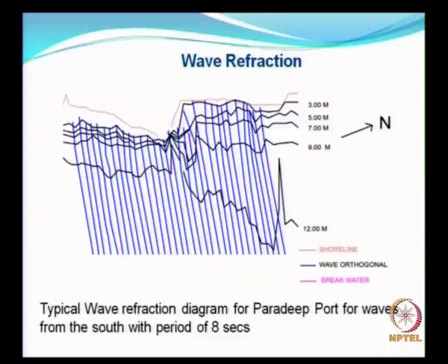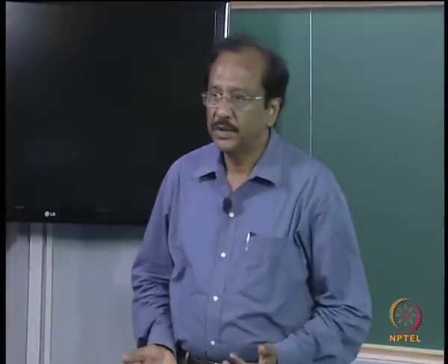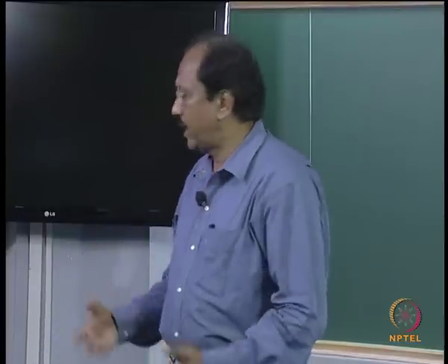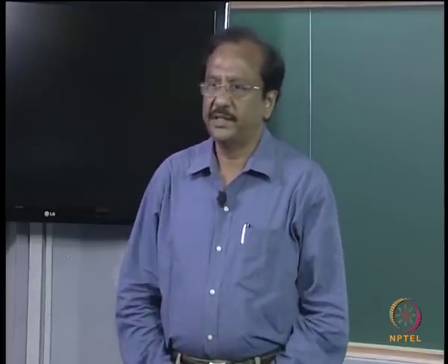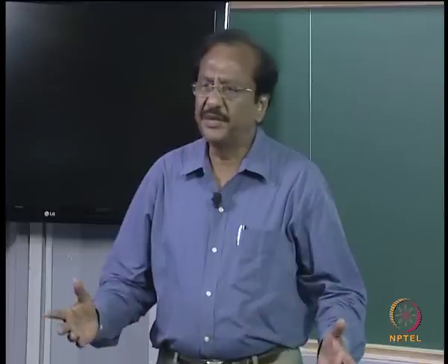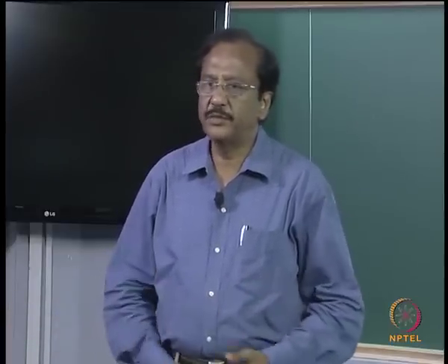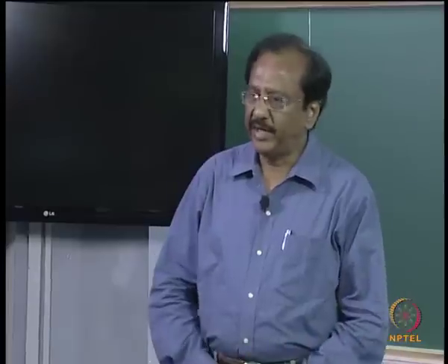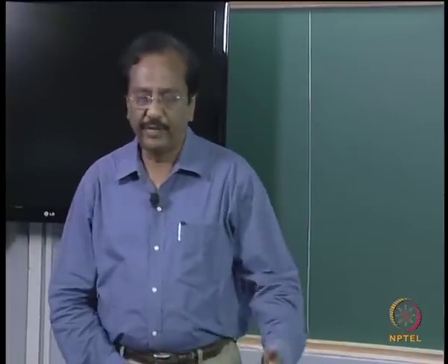and for a given wave period, how do we construct the refraction diagram? You can construct the refraction diagram for a month, for a mean wave direction, or a particular season, for example non-monsoon season or northeast monsoon season or southwest monsoon season. You can take an average wave direction and then draw the wave refraction diagram.